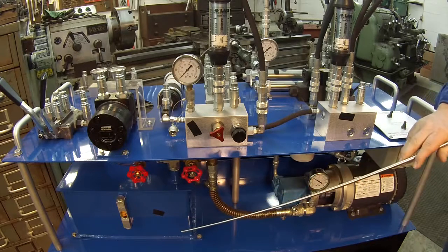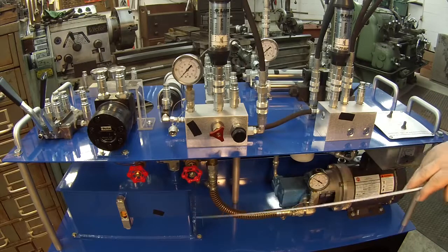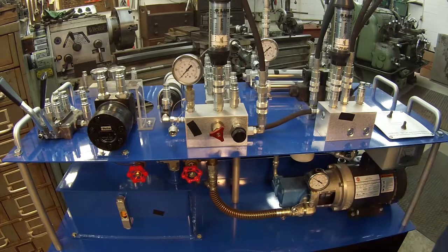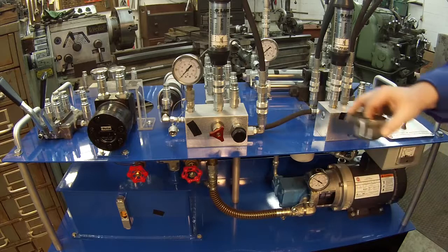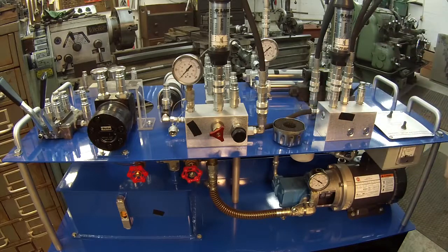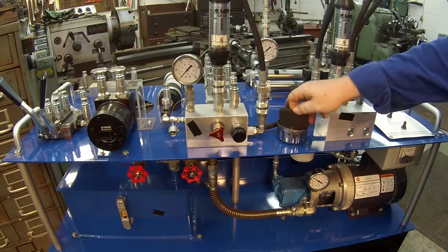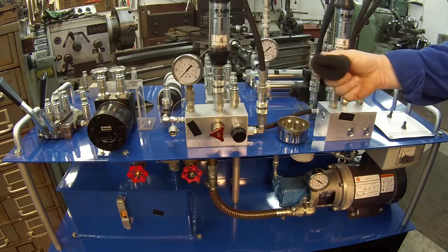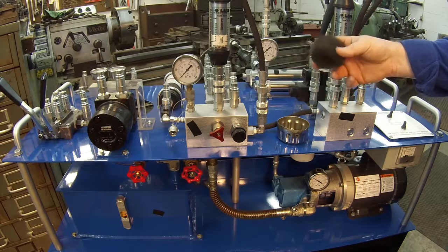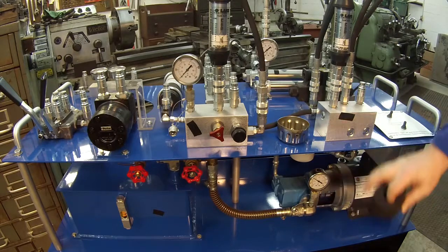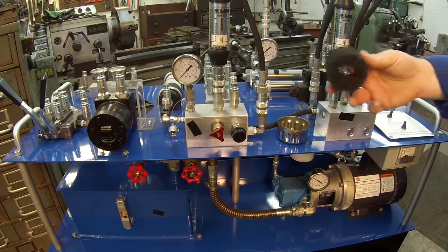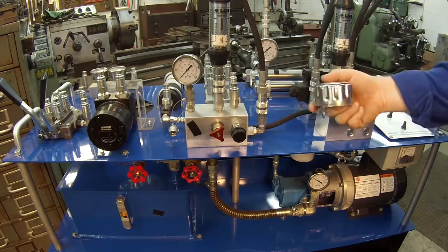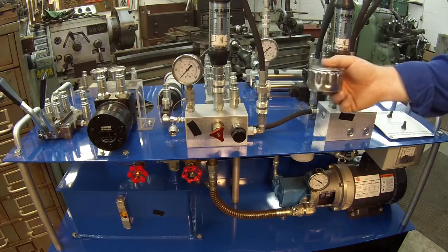Alright, how they fail is leaks, obviously a safety hazard, and clogged breathers. There's a breather up here on top of the reservoir, and I've got one of these breathers taken apart so you can see what's inside of it. This is just a piece of foam, so you'll see those breathers are basically garbage. They don't catch very much. The things that I need to protect this pump from are down at the 3 micron level, and this definitely isn't 3 microns. So if you see one of these silver breathers on top of your system, it basically isn't doing very much.